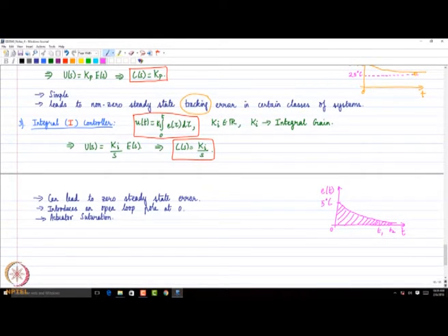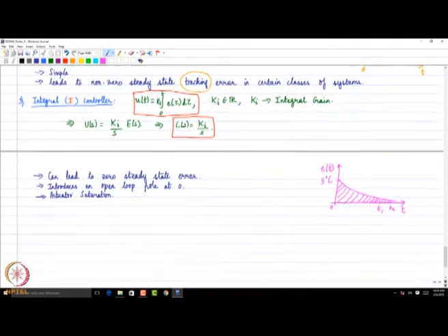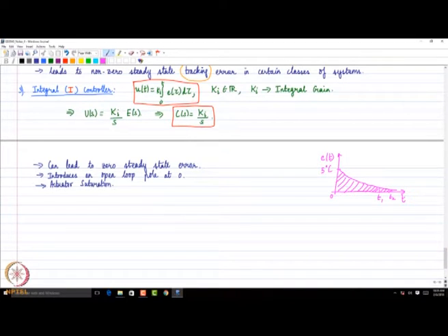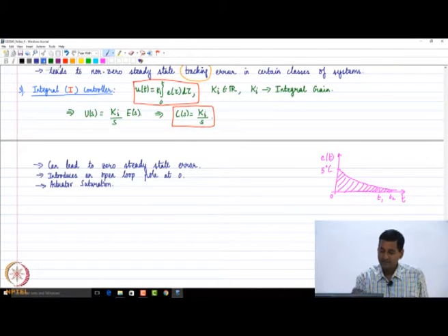So in theory, while designing, I can put in whatever value I want, but we need to be realistic about maintaining the control input within the actuator range. That is something we will also look at when we do integral control. Fine, so that is the second block. Now what is the third building block which we can use, which is called the derivative controller.